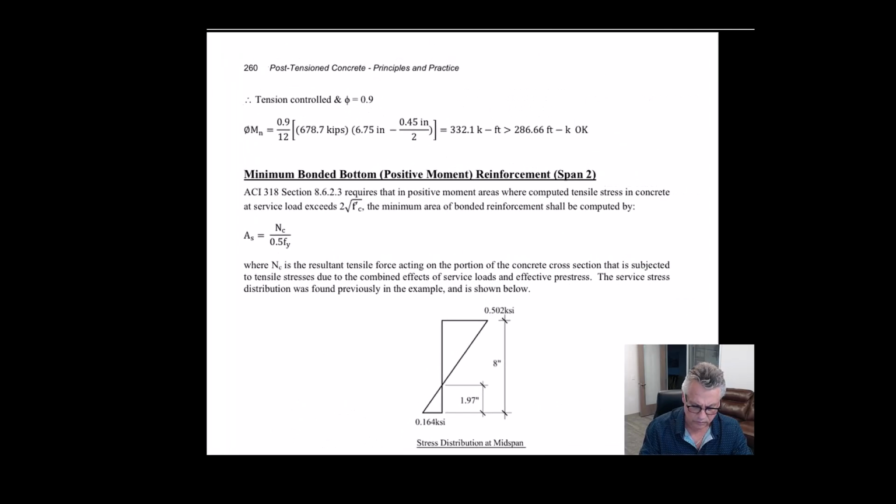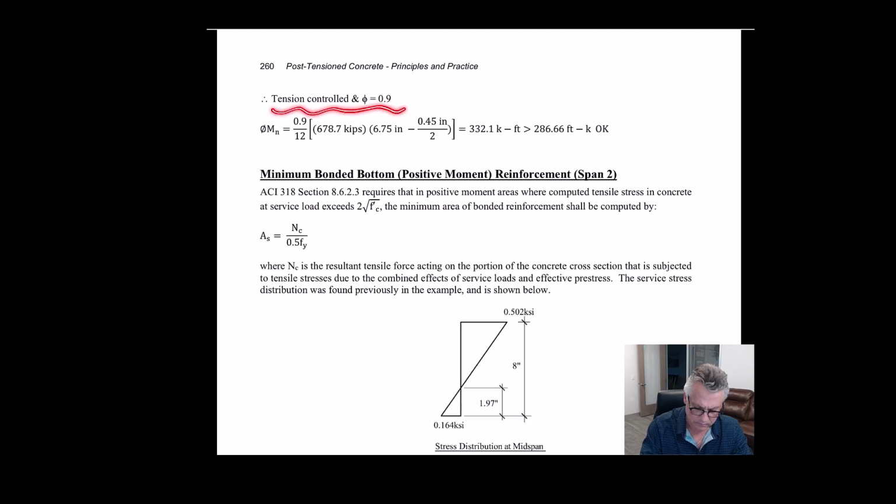We have a tension controlled slab, and we sum moments, same thing you've always done, and find out that we have substantially more strength than we needed. Remember, the controlling demand moment was on the inside, the longer span side of the interior joint. And just minimum rebar with the post-tensioning that we have easily satisfies that.